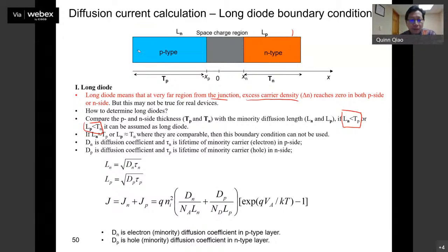Okay, the saturation. That's what it is. And then on this side, basically it's what? They tell you when you add bias, right? See here, when you add bias, basically your electron concentration will increase exponentially. That's why it's exponential, right? And then you still have the saturation current, you basically minus that. Yeah. Why is that? You can think this way.